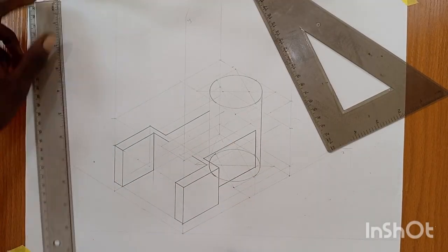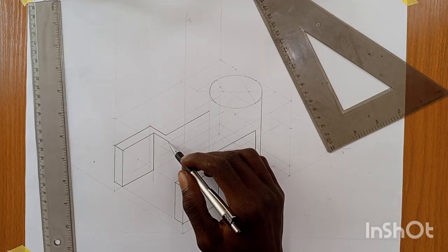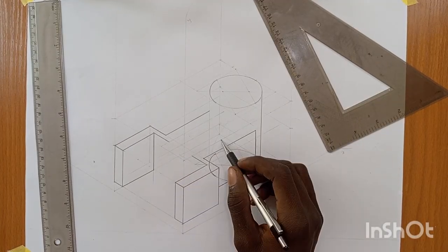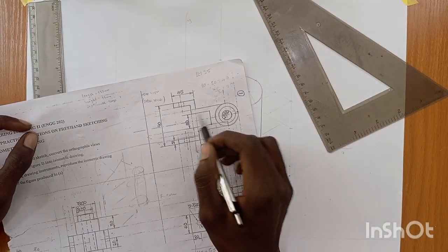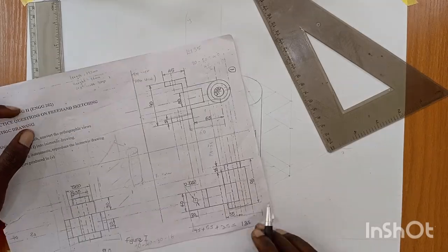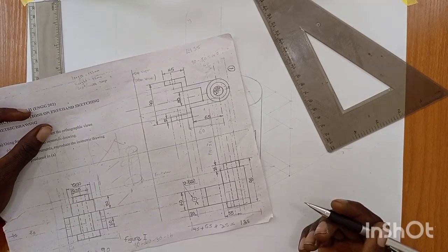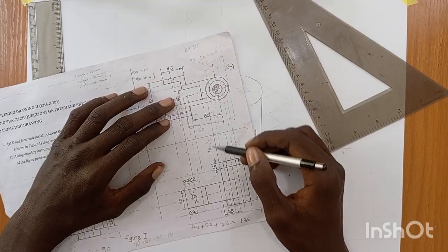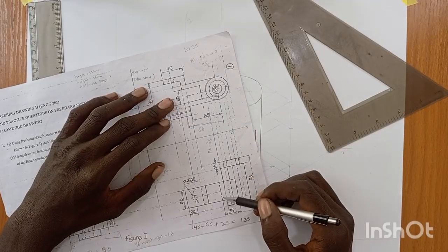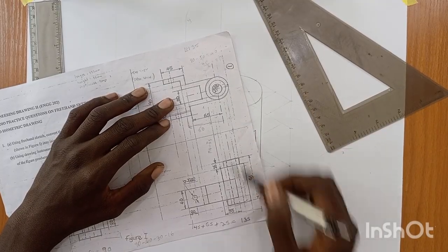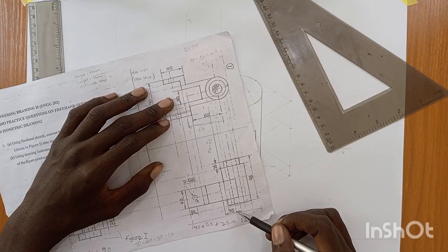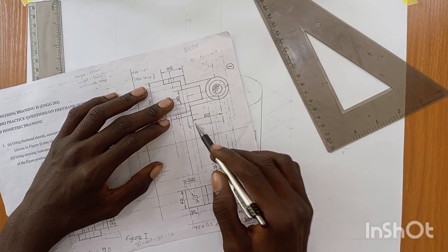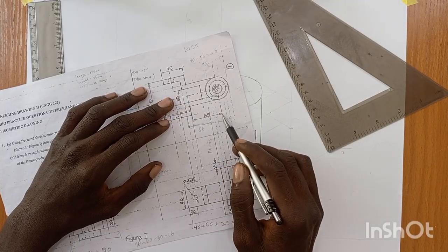Okay. So now, the next thing to do is to take this line inward as well as this outward. How do we know the length to which this goes inward? It is not given. Therefore, we have to compute it. Now, how do we do so? We can see from the top view here, to switch downward, it comes here as one hidden line, right? And the length from this hidden line to the center of the cylinder is 35. Let's keep it in the back of our mind, 35.